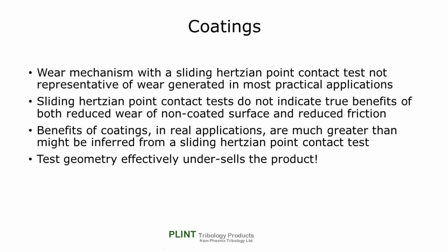The benefits of the coatings in real applications are much greater than might be inferred from a sliding Hertzian point contact test. This test geometry effectively undersells the product. It follows that to demonstrate the benefits of a coating in the majority of its intended applications, only tests involving low intensity loading are appropriate.